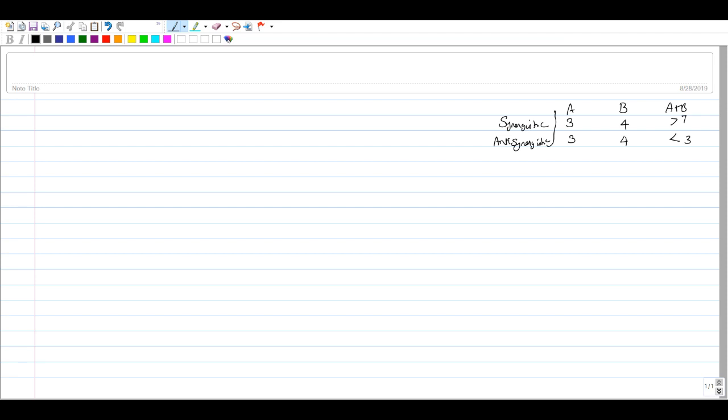That is one level higher than that. So we have discussed different levels and the line plots that you can do between the levels, from which you can even identify optimal combinations that are not part of your design of experiments. If it is not a full factorial experiment, then you might have combinations that are not there, as you might get them as optimal combinations.